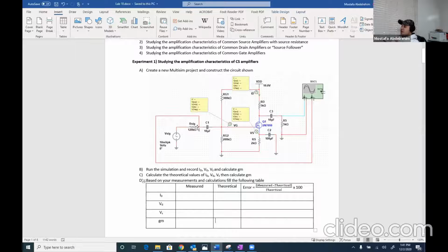And we should see here half of this because the input is equal to the signal multiplied by our input over our input plus our signal. So the AC voltage at that point here should be half of this one. Or GV should be half of AV. That's it.